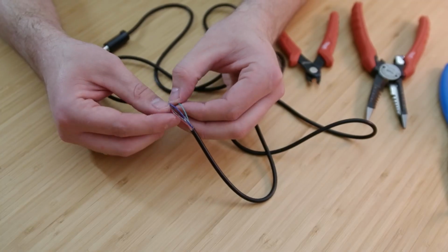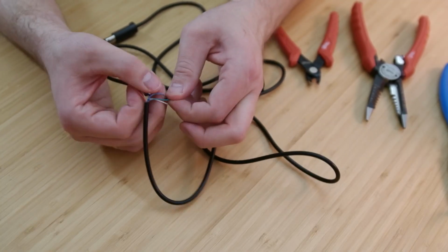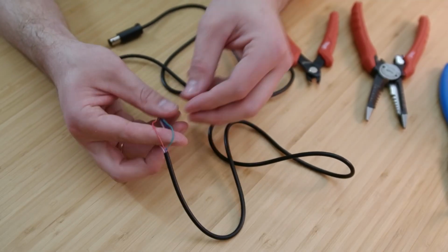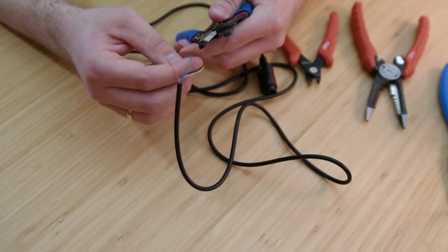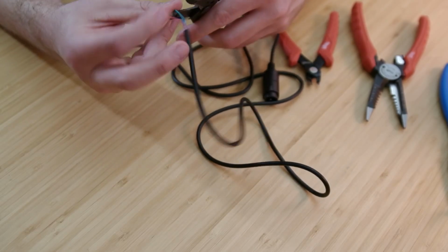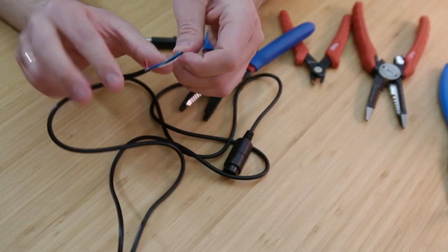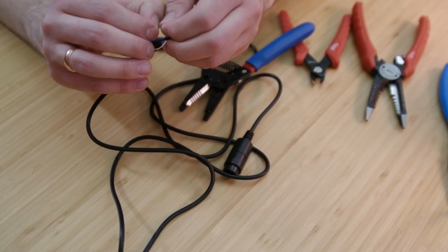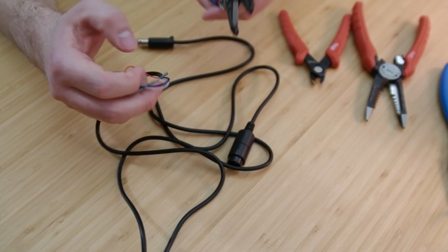In my case, it is green and red, but that can vary depending on the extension's maker. So with those revealed, I then use another wire stripper to get the 26-28 hole and strip them. They're much easier to strip because you just need to reveal a little bit of the wire so the oscilloscope's probes have something to connect to.